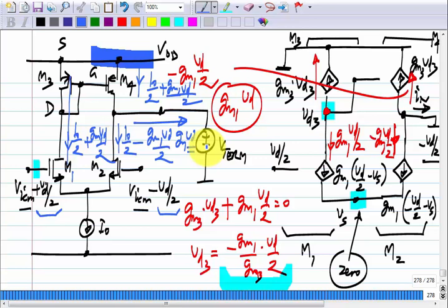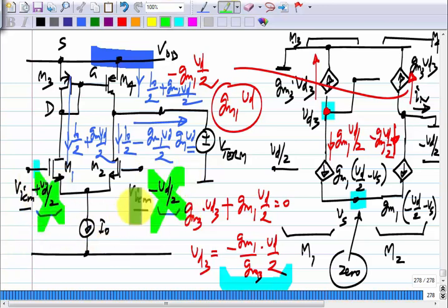So, now what else is there to be found? We have to find the output resistance. That thing is the same for Thevenin and Norton. Essentially, what we have to do is we do not have any incremental input. We null the incremental input. The operating point will remain exactly the same, and we find the resistance looking back that way.